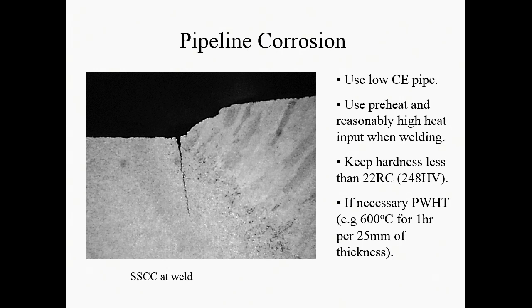So people who work in the marine environments know this. They always do a separate painting operation on top of the weld, and then they paint the whole system afterwards to make sure that you've got extra corrosion protection on the weld and weld region. They even paint it in a different colour to make sure that it's been done, so that you can see that it's there. So you have to think about that.